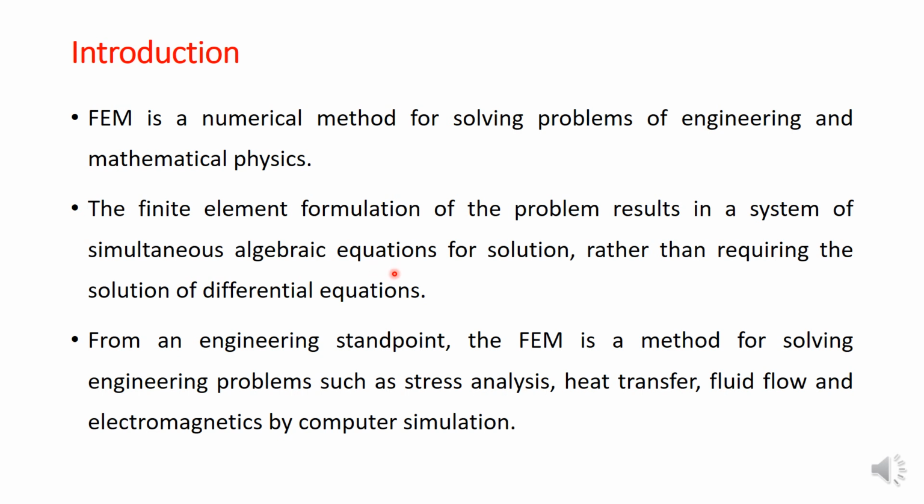From an engineering point of view, we can apply FEM in many areas, such as stress analysis. The primary unknown while we deal with stress analysis would be the displacement. Then we can find the strain, and once we have the value of strain, from the stress-strain relationships for the problem, we can find the stresses.